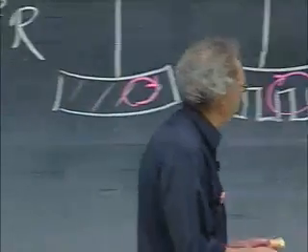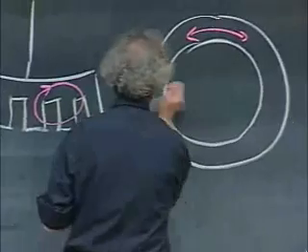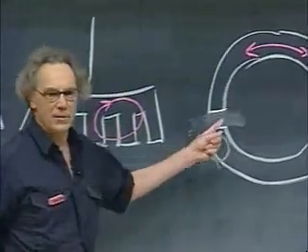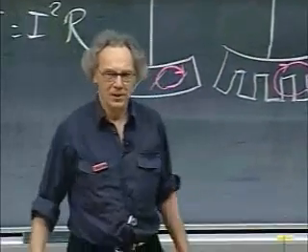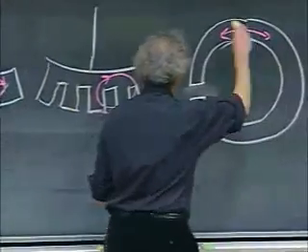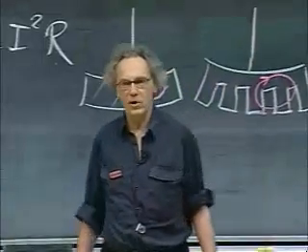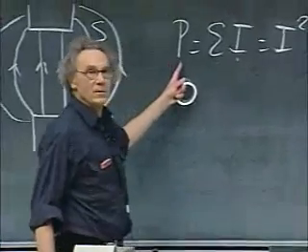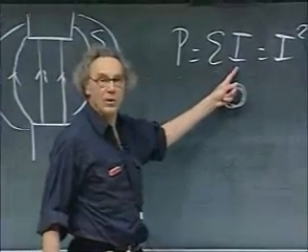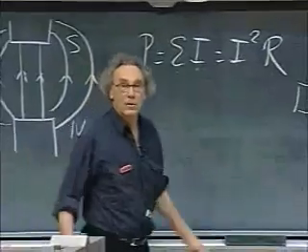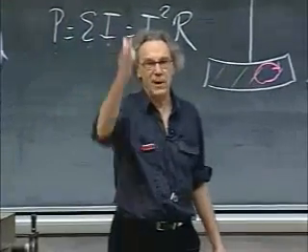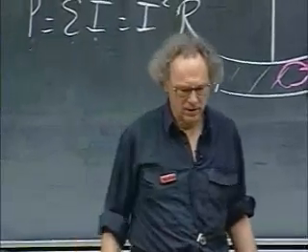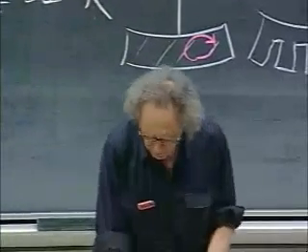And then I will throw through there another ring, which is the same dimension, but this ring has an opening here. Air, the resistance is huge. So the current that is going to flow, this eddy current, is way lower because the resistance is so high. And so there is no power dissipation because I is so low, and so there is no heat produced at the expense of kinetic energy, so there is no damping. There is no force, no strong force that opposes it. And I can show you both.